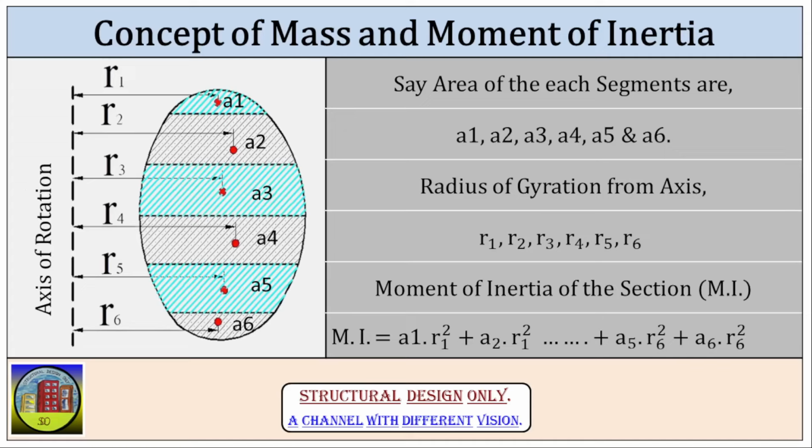There's a catch, though. To get the correct moment of inertia, you need to multiply the area by the density of the material and the thickness of the plate. So, remember, moment of inertia usually depends on how the mass is distributed, but for special cases like thin, uniform plates, area can be a helpful substitute.